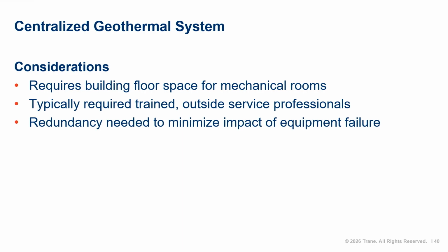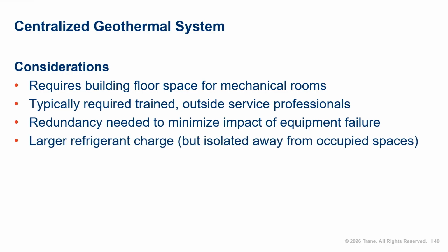Redundancy must be purposely designed into the system to limit the impact of equipment failure. And the central heat pump equipment has a larger refrigerant charge than the smaller distributed units. However, this charge is isolated away from the occupied spaces.